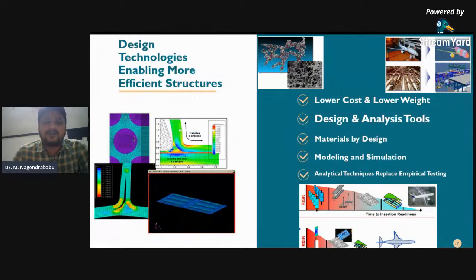New materials adoption is happening exceptionally quickly in aerospace, requiring DFM-minded interaction between material characterization and component design. The two must be in balance, and one can't really exist outside of the context of the other. Meanwhile, one-piece designs are continuing to reduce the number of components in overall assemblies. In general, this bodes well for composites in aerospace, which can be formed instead of machined.